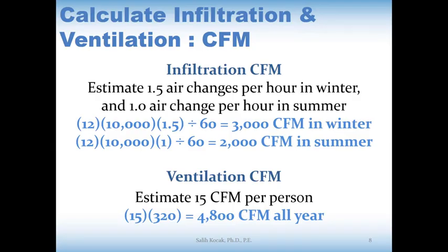So during the summertime, there will be 2000 CFM from infiltration and 4800 CFM for ventilation. So the total is 6800 CFM during the summertime. And in winter time, 4800 plus 3000 is going to be 7800 CFM.